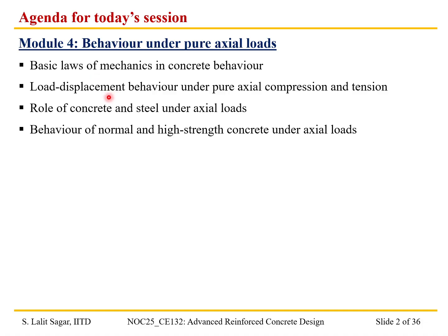Then we are going to study the load displacement behavior of the reinforced concrete members under pure axial compression and tension. Then we're going to be studying the role of concrete and steel in resisting the axial loads, that is, what percentage of the load is being resisted by the concrete and steel respectively. And finally, we're going to be studying the influence of the behavior of normal and high strength concrete under the axial loads.